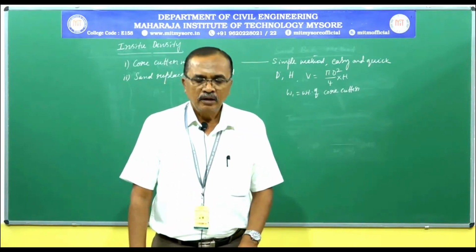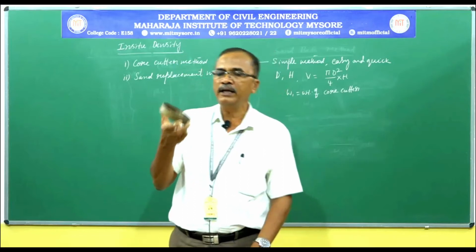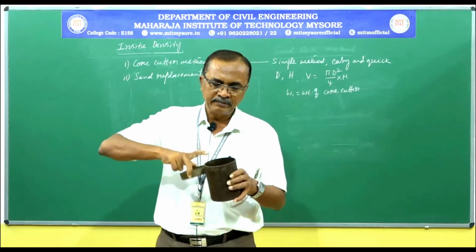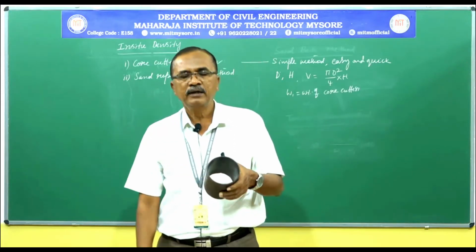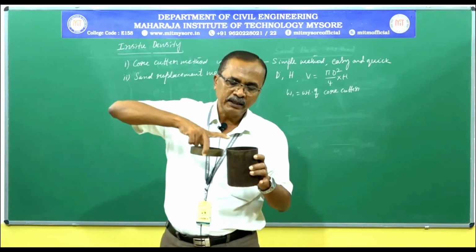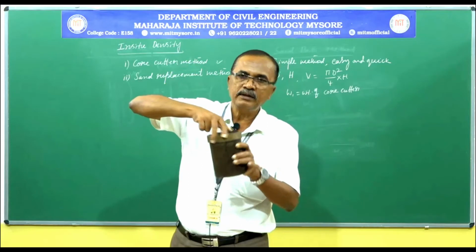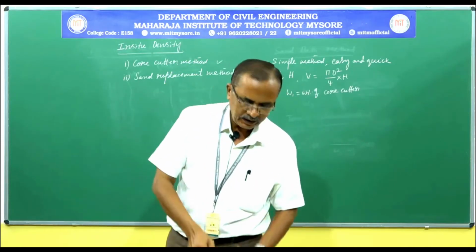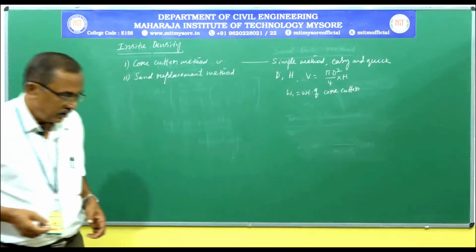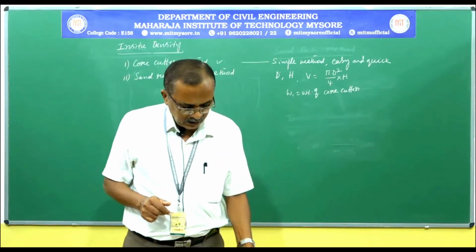Next, before proceeding to the field, we use a collar or a dolly. In other words, we call this a helmet, to protect the head of the core cutter. The blunt edge is called the head and the sharp edge is the cutting edge. The collar will fit perfectly on top, like a helmet. We decide where to conduct the test, and we take this to the field.